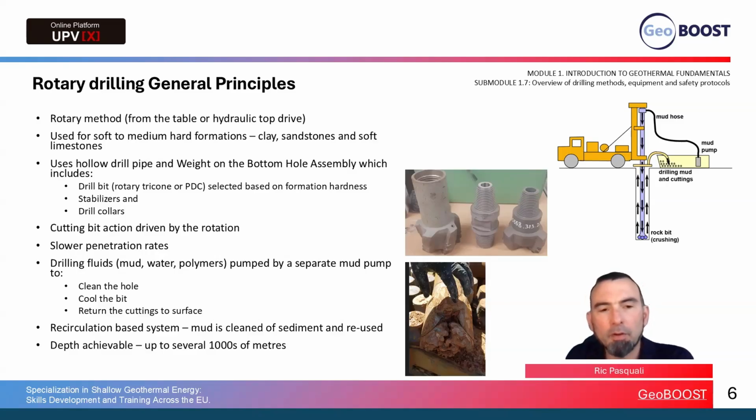The key thing to remember about this drilling method is that it generally has slower penetration rates than other methods that we will discuss. But the point here is that this method uses a drilling fluid to clean the borehole, cool the drill bit, and bring the cuttings back up to the surface, as you can see on the diagram on the right-hand side. The point of this system is that it is sealed and it is recirculated. The mud and the fluid is recirculated once the mud is cleaned.